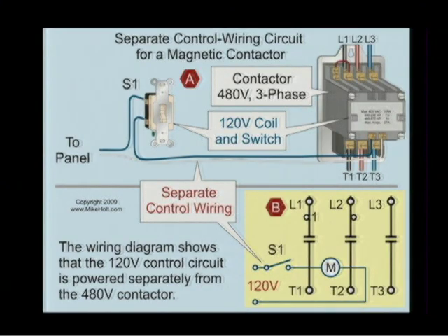So if you knew in advance what you want, you just order the one with the 120 volt. But if you don't know what you want in advance, you're just going to end up with whatever they have on the shelf. Gotcha. Yeah, makes sense. One other thing before, if you look at figure A versus figure B, notice in figure A you're not using the overloads, the overload contact, whereas in figure B it tells you that. So I mean that's what's nice about being able to start to understand the symbols and looking at the figures.